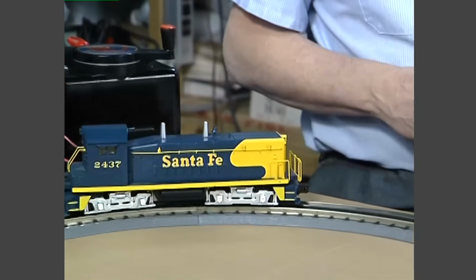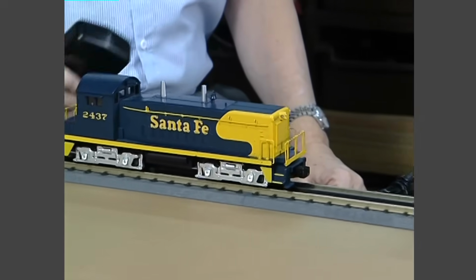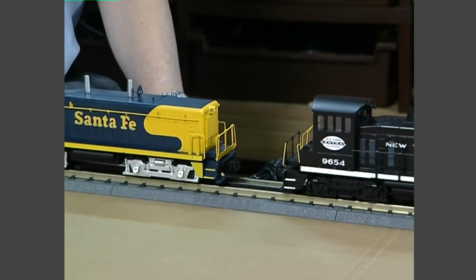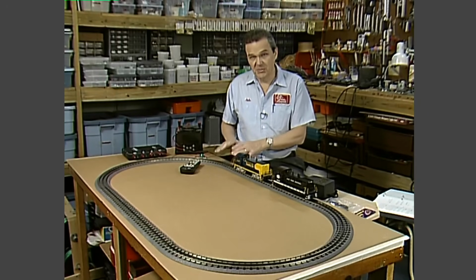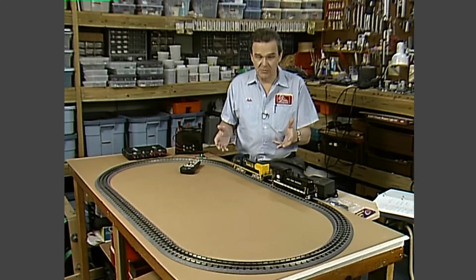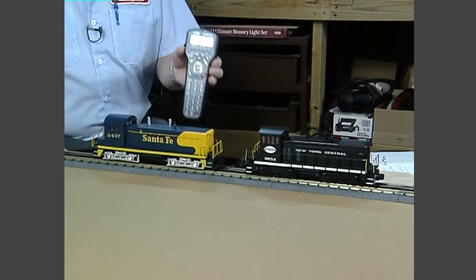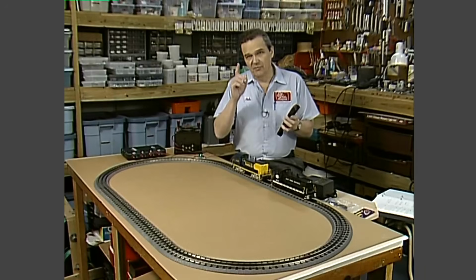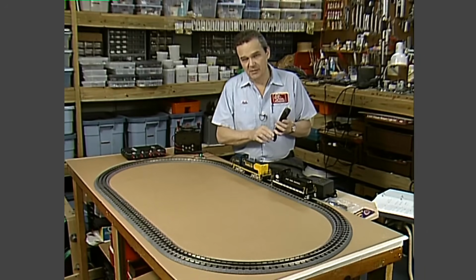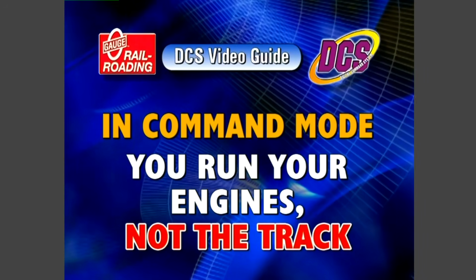So, what have we learned? We've learned that in the old conventional mode of operation, we had no way to control engines separately if they're on the same track. The engines all get their instructions from the track, and since they're all on the same track, they all get the same instructions whether we want them to or not. In command mode, we found that we can control each engine separately, even though they're on the same track. And that is the fundamental difference between conventional and command modes of operation. With command control, you run the engines, not the track.